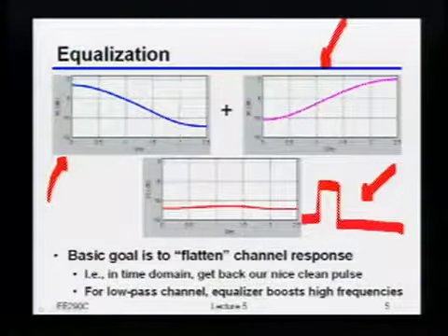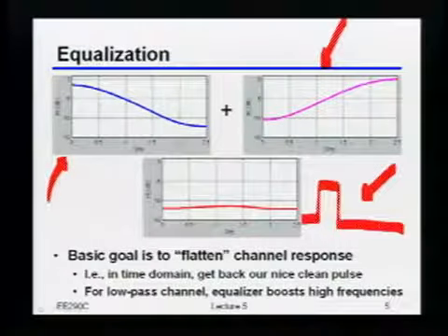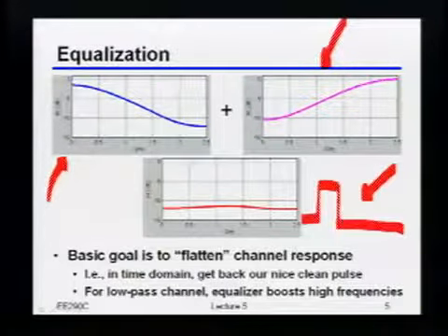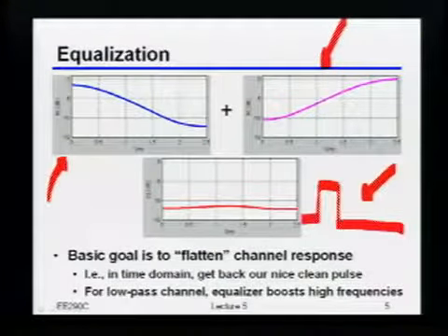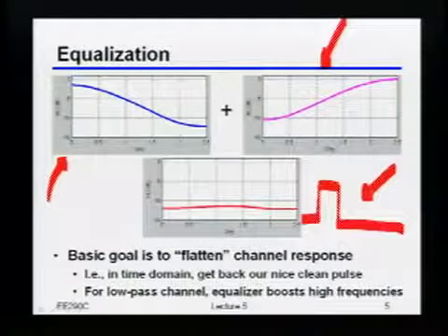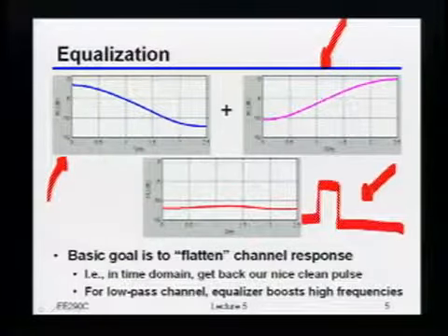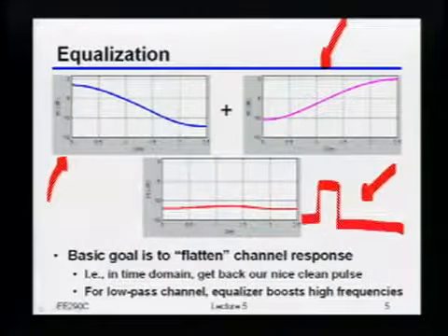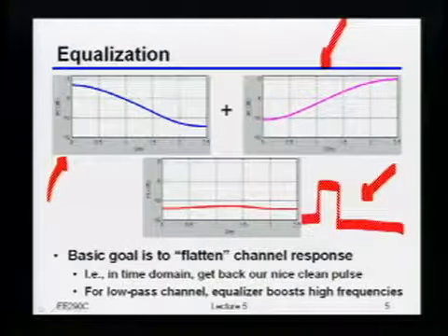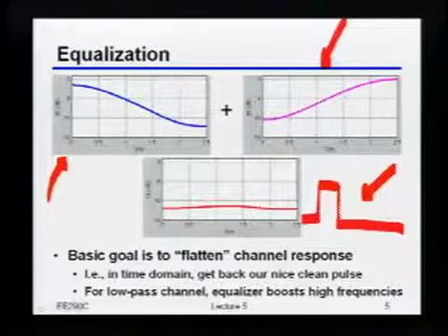Yeah? So I have a question. In all this, you have assumed that the channel is linear. How do you justify it? Okay, well, the good news is, if you remember I said way back when that usually the backplane is passive. So unless I'm doing something really nasty, most of the time it is justified to treat it as a linear channel. Unless I have voltages so large that I'm melting metals or dielectrics or something like that, it does look very much like a passive linear channel.